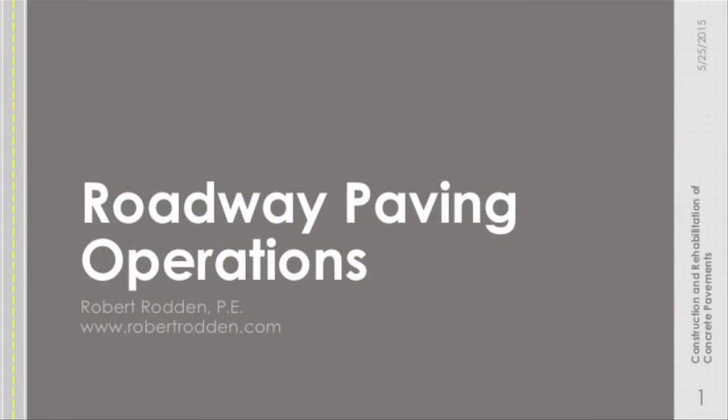So we're past the pre-paving stuff. Now we're finally time to talk about what we're here to talk about, the construction. So we're going to talk mostly in the beginning about slip-form paving because it is the more complex and difficult to understand, but it's the most economical way of constructing concrete pavements of any significant scale.